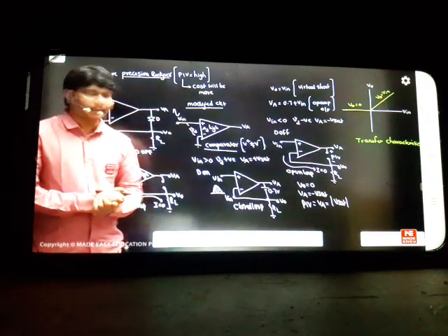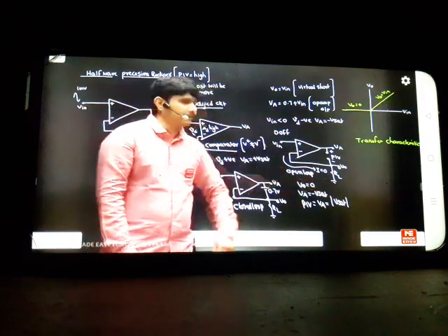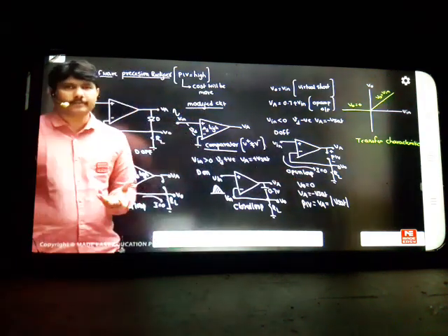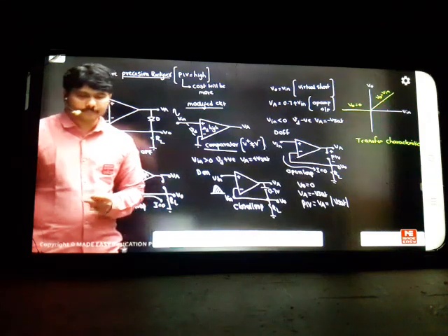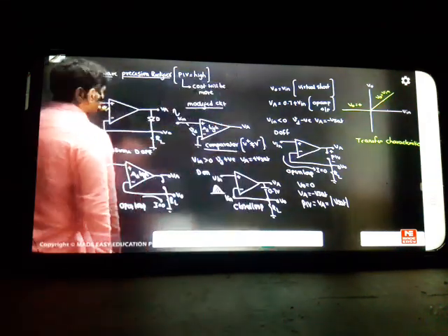Yes, Sridas, what you said is exactly correct. Here, no current is flowing, because in an op-amp, no current can enter. And not only that, there is no potential here either. If you don't give any potential, no current will enter the op-amp, so I minus will be 0. If I minus is 0, it means I equals 0 in the port. So this completes the situation. If you want, you can write that note here only, on the same diagram in the exam.